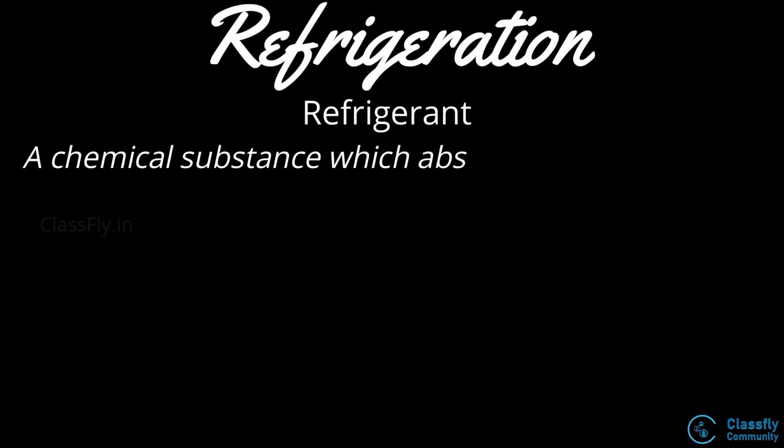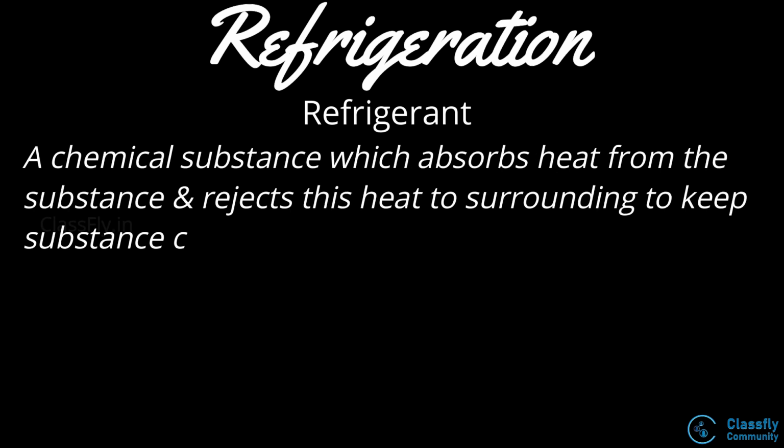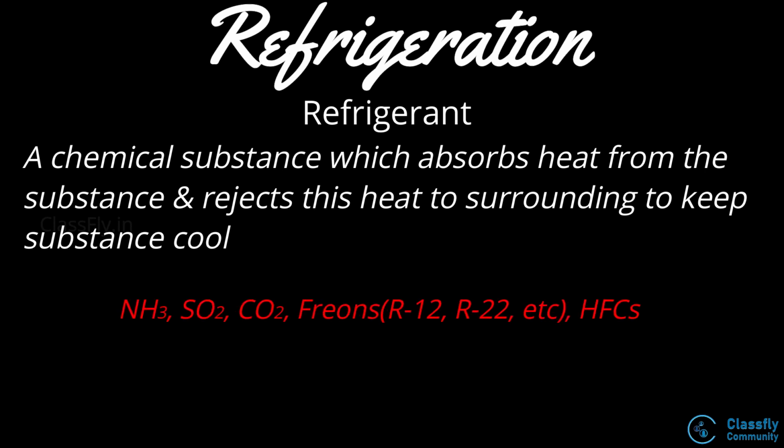Well, refrigerant is a chemical substance which absorbs heat from the substance and rejects this heat and hence keeps the substance cool. Then we studied about the properties of the different types of refrigerants such as ammonia, sulfur dioxide, carbon dioxide, freons such as R12, R22 and then HFCs.